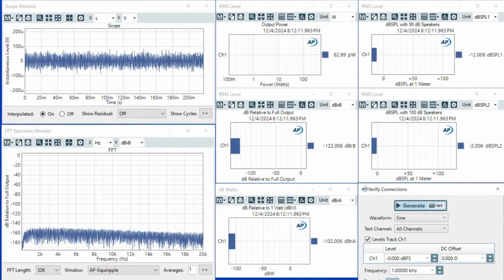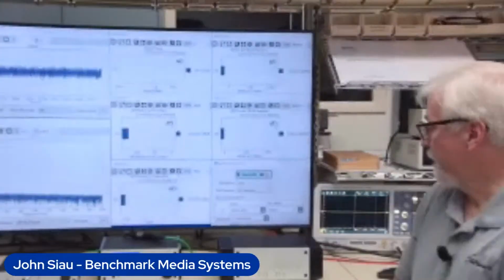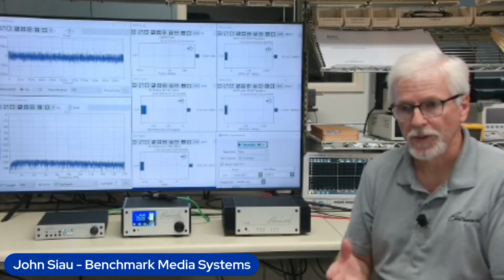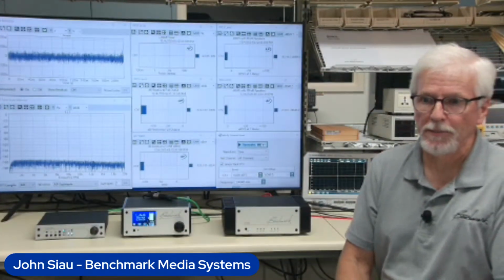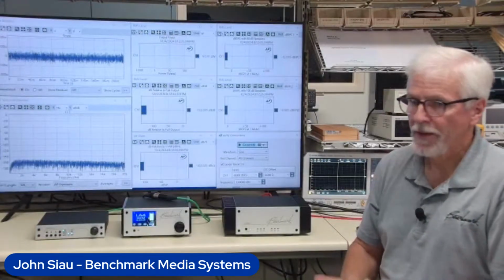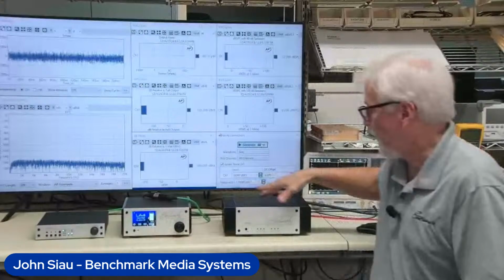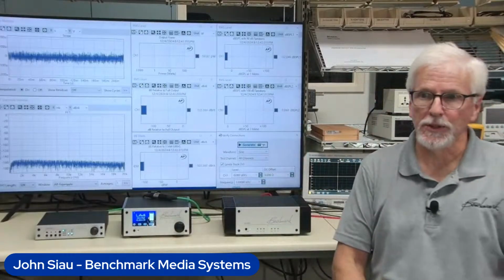It just turns out that that's where the DAC needs to be running when it's hooked directly to the power amplifier. The reason we have it set at -2 dB is we wanted to give you some room to turn the volume up if you've got a weak signal, and it also allows you to overdrive the amplifier slightly. That's just the way we chose to match the DAC3 to the AHP2.